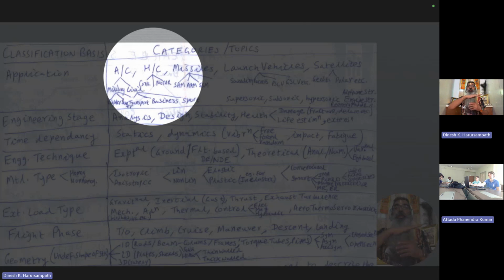In particular, from a structural point of view, it is the extension and the twist which get coupled, and because of that, there can be certain issues. But if it is done properly, it can be to an advantage. So whatever causes harm, if you look at it from a different perspective, can cause benefit as well. In other words, many of these couplings, especially the ones that come from geometry and or material, are usually double-edged swords. So you can either use them or misuse them, or suffer because of that.